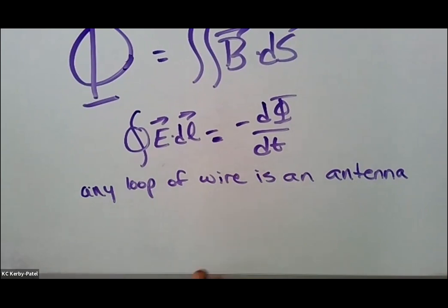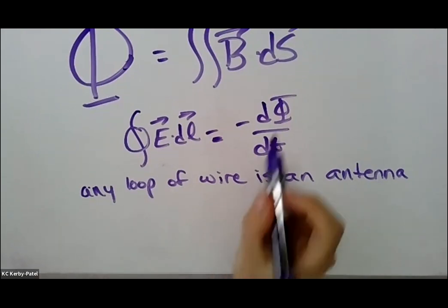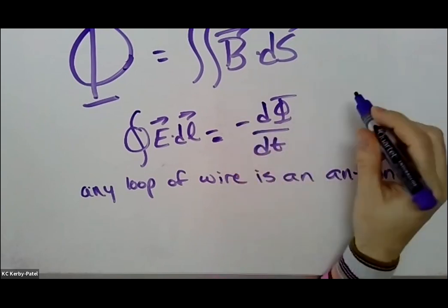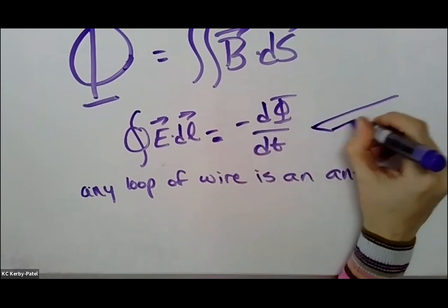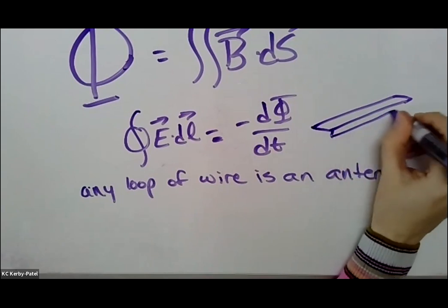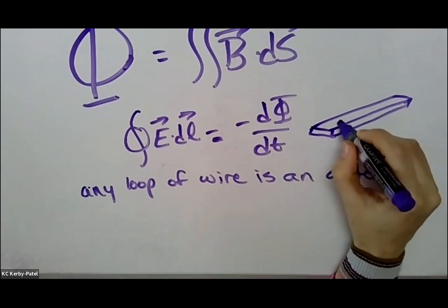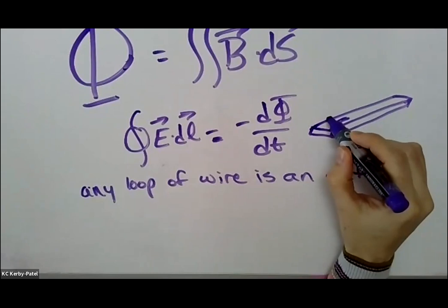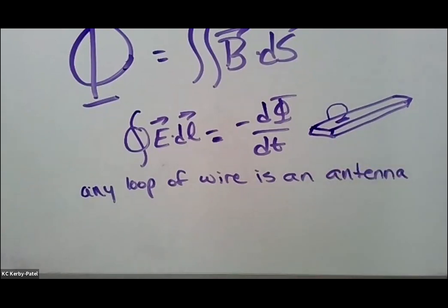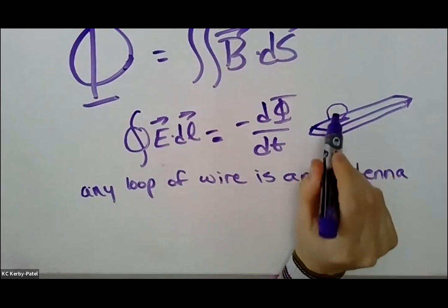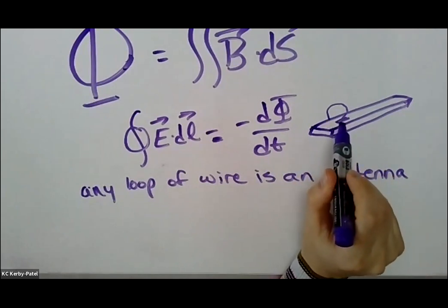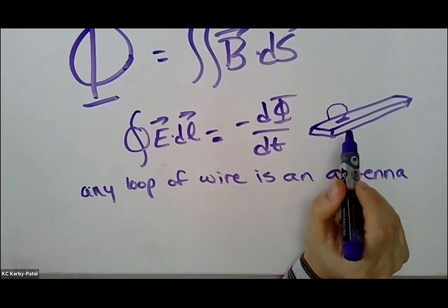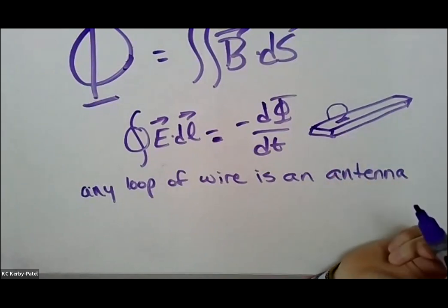When you're wiring a breadboard, any loops that stand up away from the breadboard can have a magnetic flux pass through them. So if your breadboard, for instance, has a chip on there, and then you have a big old loop of wire connecting the chip to something, magnetic flux can go through there. So you can get currents induced on this thing from somewhere else, some other device, some other circuit, from solar flares. Anything can happen.